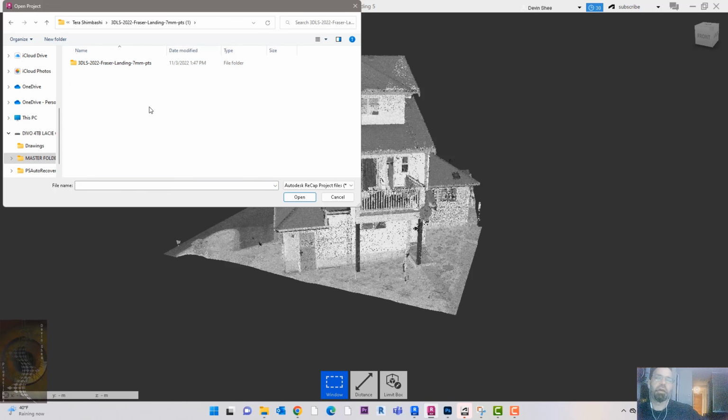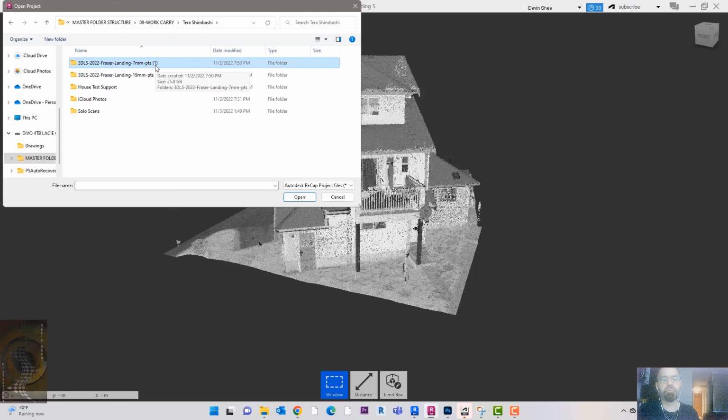So what that kind of theoretically means is if you zoom up to a space that is, let's say, 25 millimeters. If you have a 7mm decimation, theoretically that would mean that you would see 4 points because they would be sort of spaced at 7mm. So space of 24, you would see 4 points. If I set that at 20, I would only see 2 points.